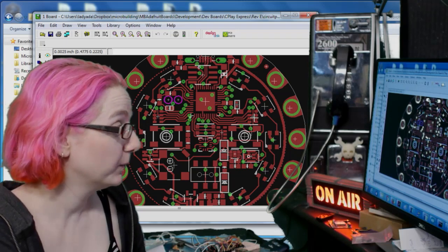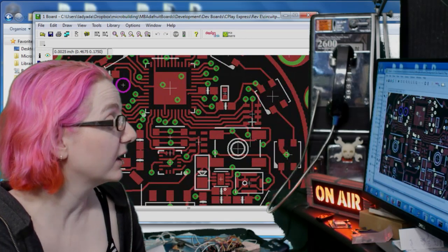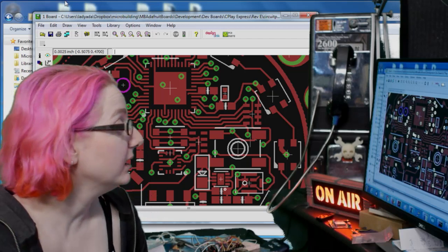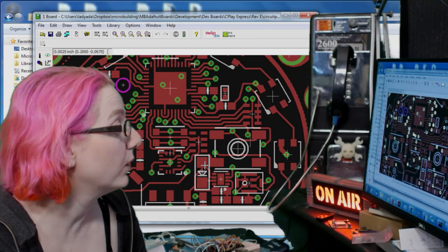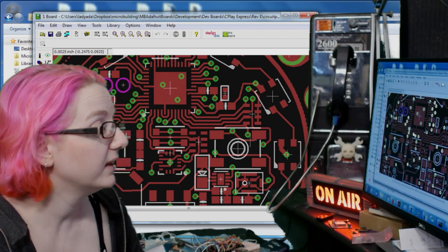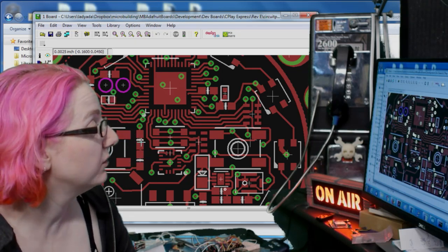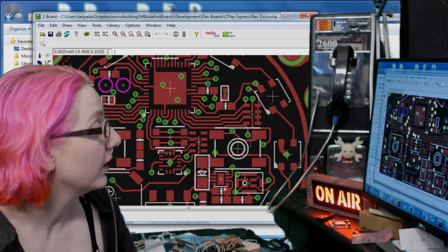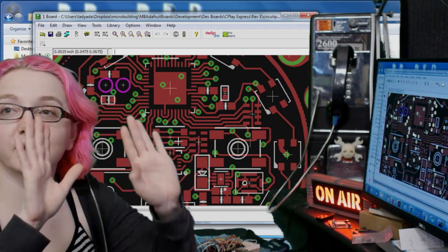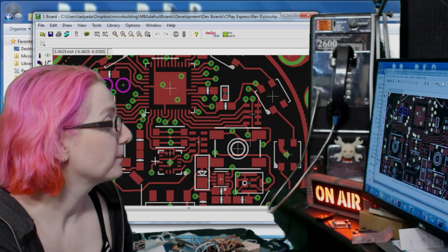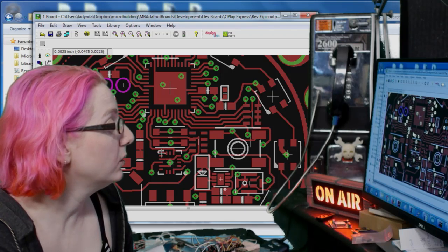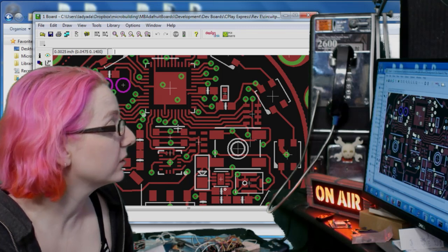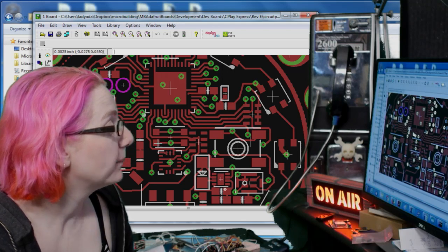So what I'm hoping is when I get rid of these resistor packs, it'll free up my routing space a little bit, so that what I'd really like to do is put one of these LEDs over here, and then the other LED over here, and then I would move these 2 components up here perhaps, and have them come around this way. These are for the audio amplifier. And I'd like to have the IR symmetric around the accelerometer. So I might move some stuff too. Like I might move the reset button down instead of up to make it closer, but I'm not exactly sure yet. But that's my goal here.